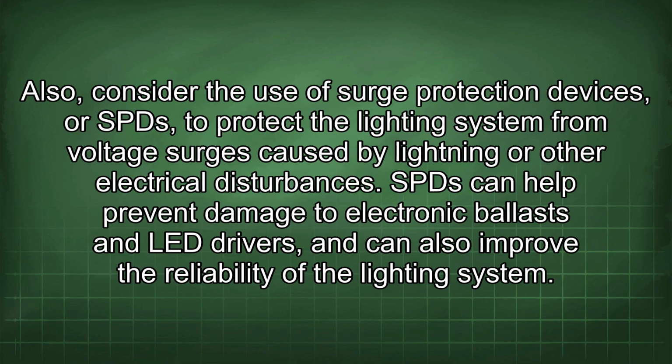Also, consider the use of surge protection devices, or SPDs, to protect the lighting system from voltage surges caused by lightning or other electrical disturbances. SPDs can help prevent damage to electronic ballasts and LED drivers, and can also improve the reliability of the lighting system.